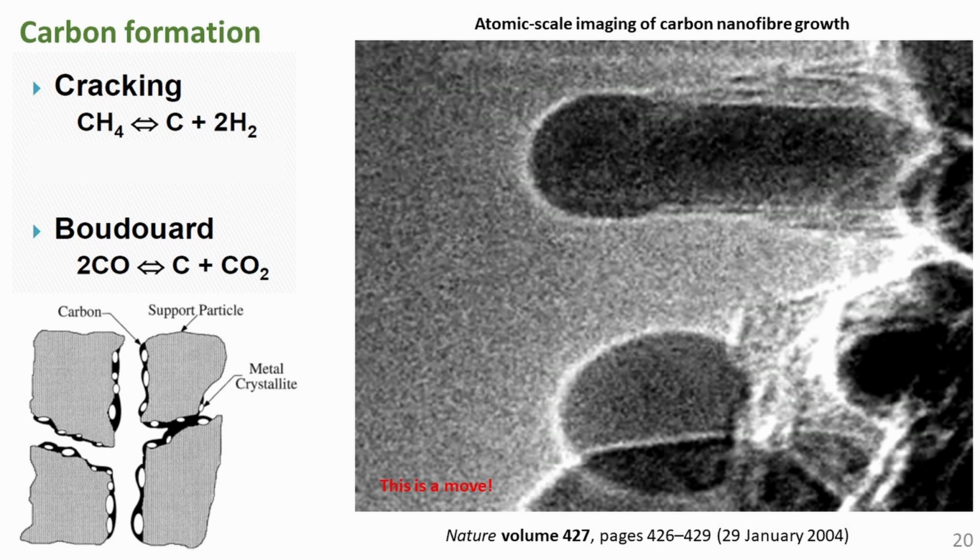I'd like to note that the nickel particle size has an impact on the nucleation of carbon. The smaller the crystals, the more difficult it is to initiate carbon formation. The rate of carbon formation was found to be far less on noble metals than on nickel.